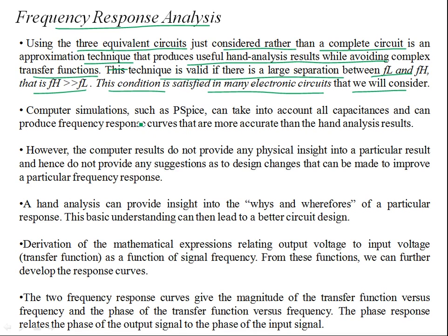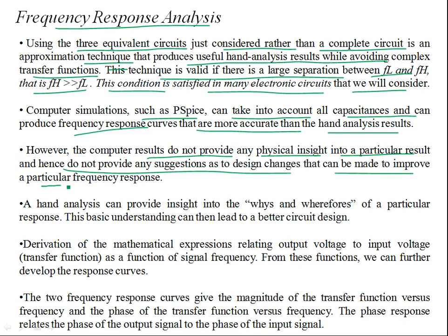Now, computer simulations such as PSpice can take into account all the capacitances and can produce frequency response curves that are more accurate than hand analysis results. However, these computer simulations do not provide any physical insight into a particular result, and hence don't provide any suggestion as to the design changes that can be made to the particular frequency response.